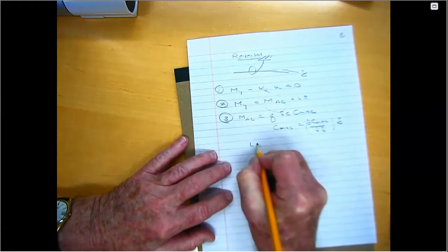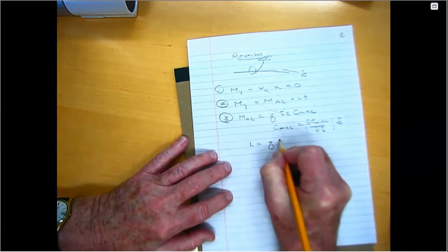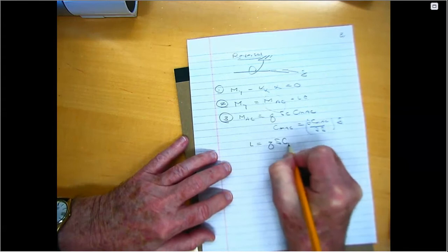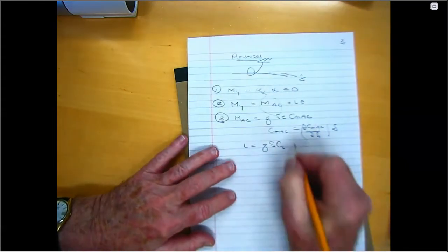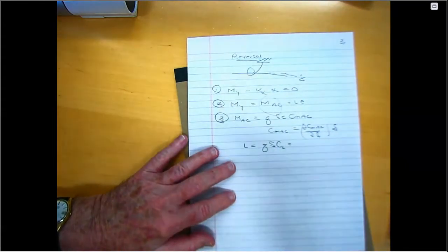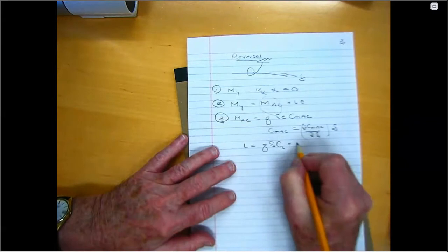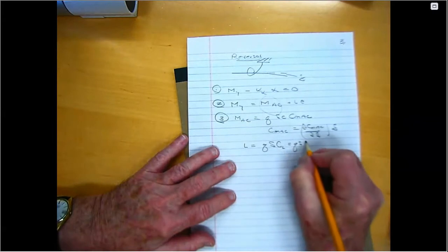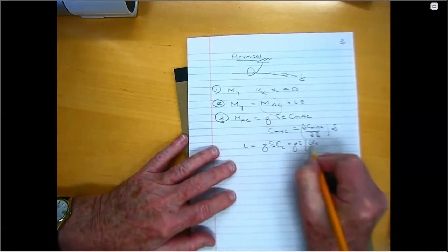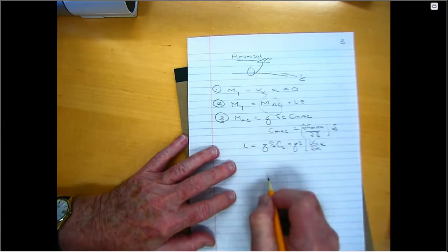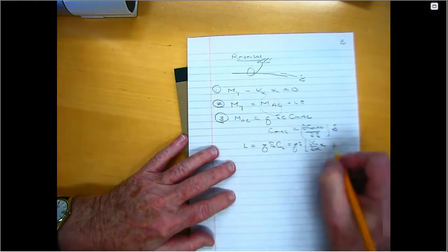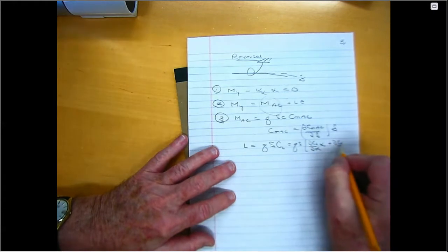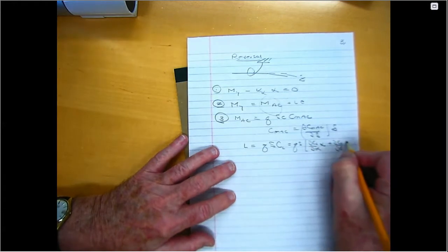3, and the same thing is true of lift. Well, lift is going to be QS times CL, the non-dimensional lift coefficient. Writing it out in more detail now, we have dCL d alpha times alpha, right? So we're also going to have dCL with respect to delta times delta.